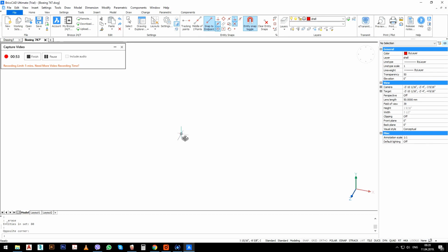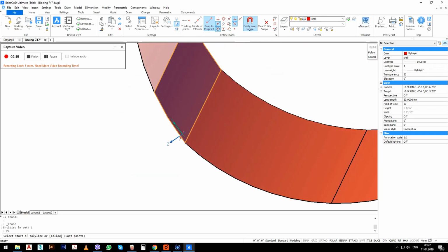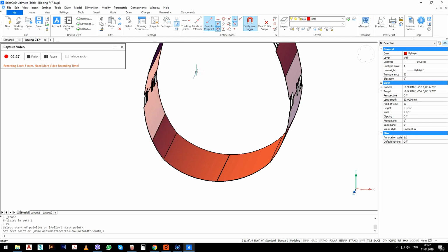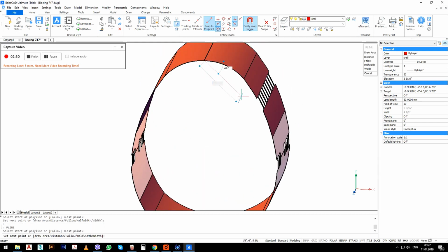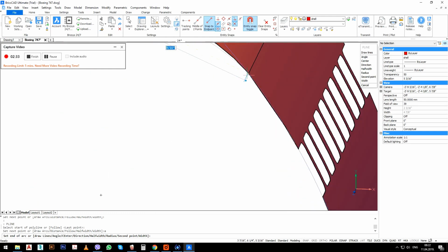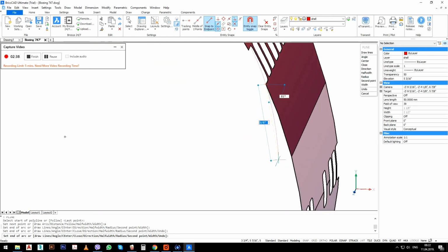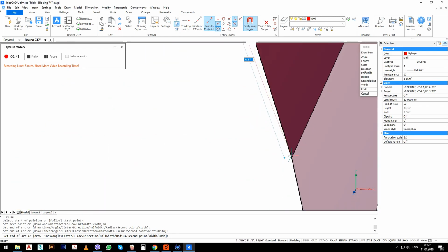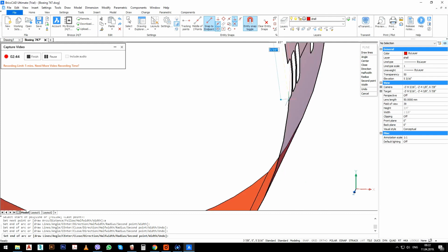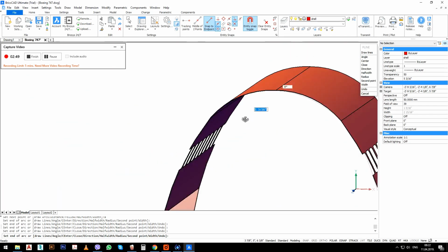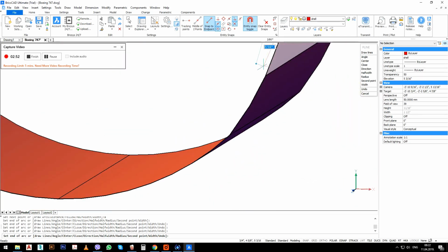Okay, now I'm going to use polyline to draw the shape of the plane. Using arc and going from endpoint to endpoint so I can achieve the same shape as the plane itself as closely as possible.